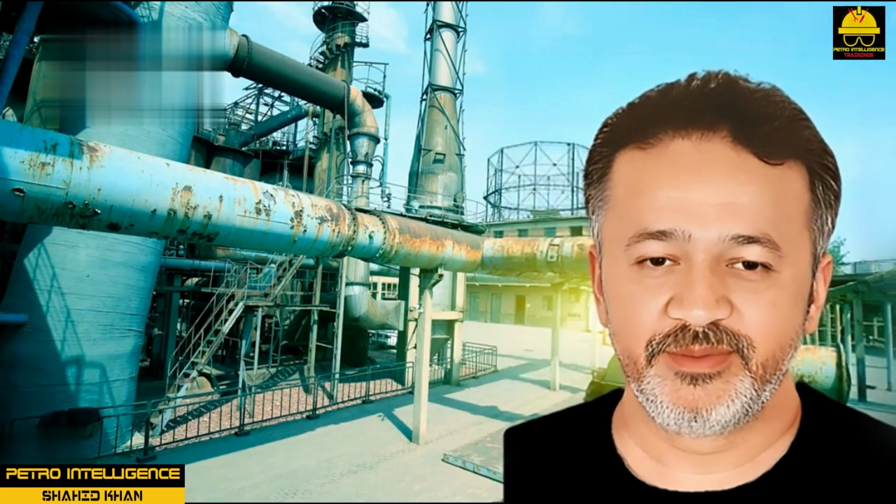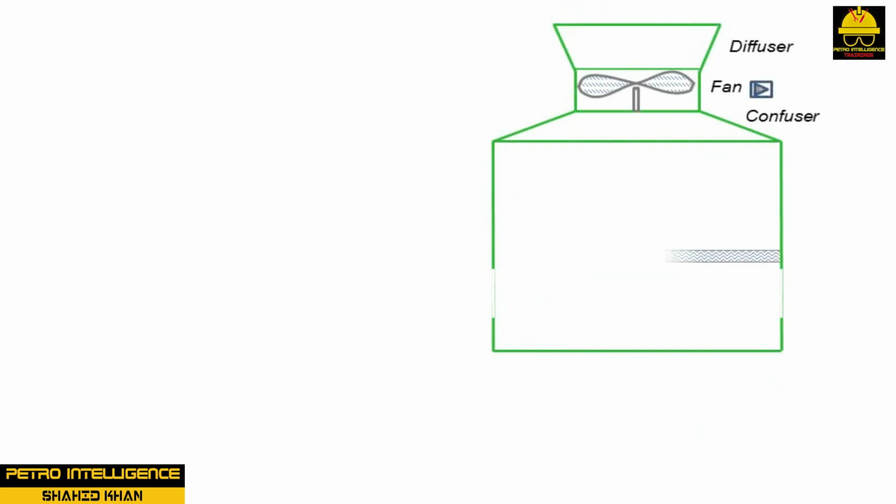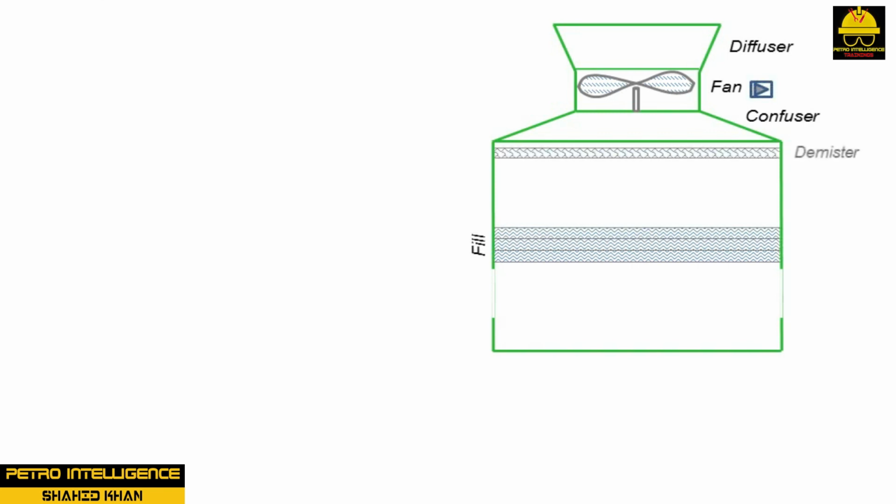Cooling water system. The cooling water (CW) system is used for cooling the various pieces of equipment in the facility in a closed cooling system. The cooling water system is divided into two complementary circuits. One CW circuit operates on a once-through basis, the other allows the reuse of water to cool a second train after use for cooling the first train.